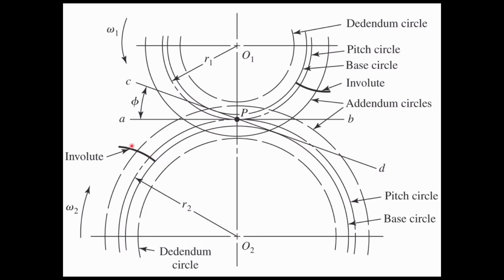In this diagram, we have the shape of an involute drawn in, and it starts off at the base circle here. If you imagine unwrapping a string and drawing this curve, it's really only defined outside of the base circle. We can't define the involute on the inside of the base circle, and that's going to become important in the next lecture. Let's go through a physical demonstration to illustrate how we can generate involute tooth shapes.